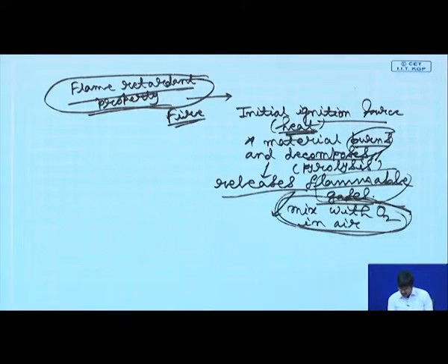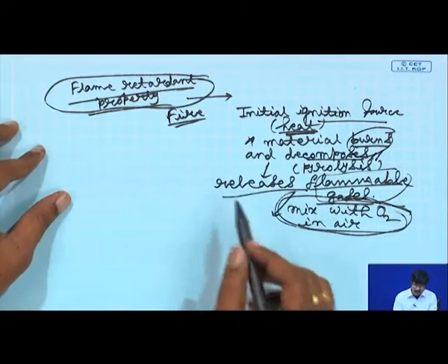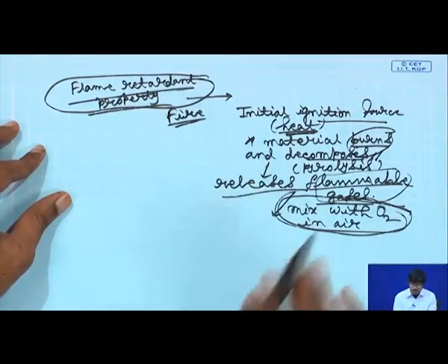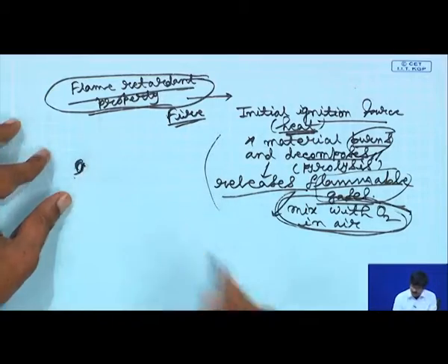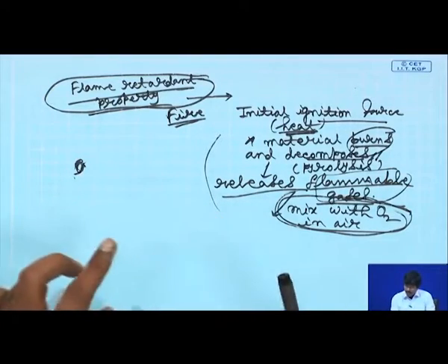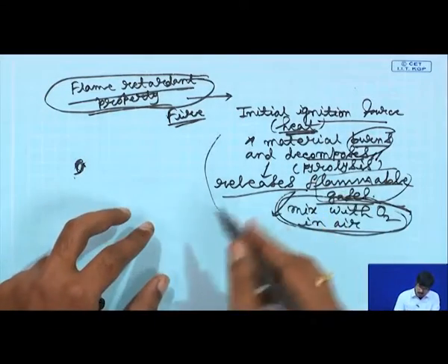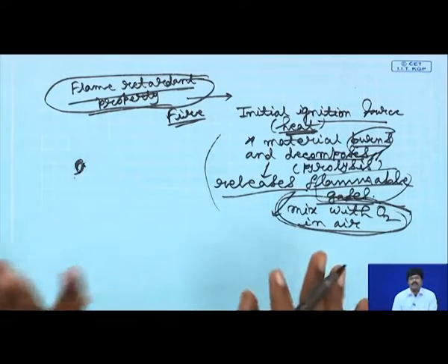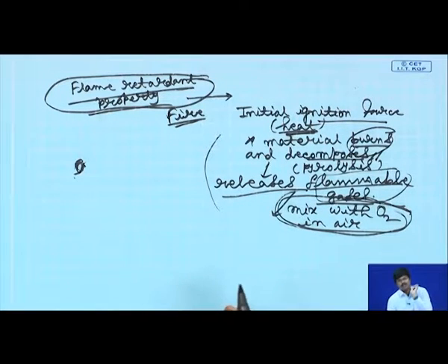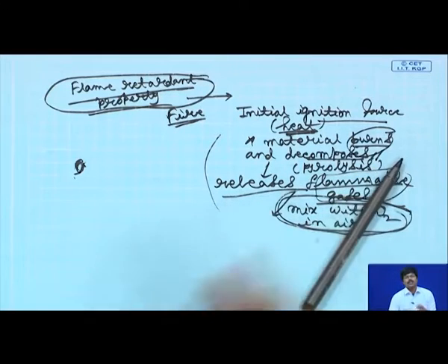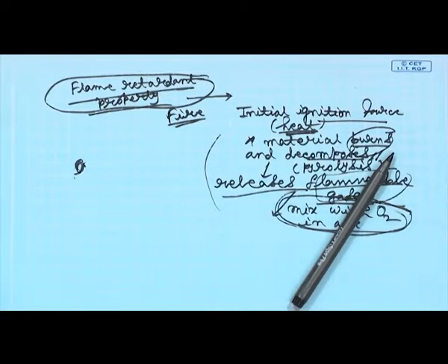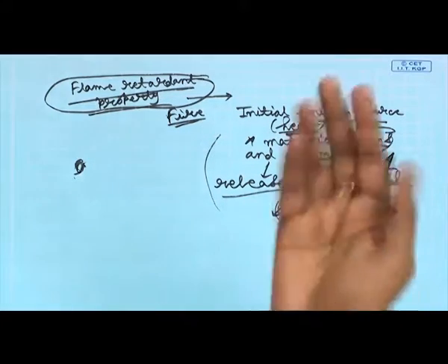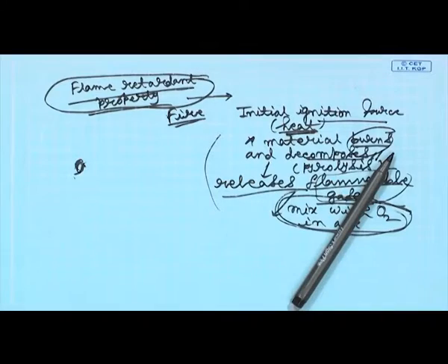Now, there are different ways in which a fire retardant could work. One of the ways is that it could stop the feeding of the combustion process. When this combustion is going on, it is releasing more heat, the flammable gas mixes with oxygen and burns, it releases more heat, and then your material burns further and releases more and more flammable gas, and so on and so forth.